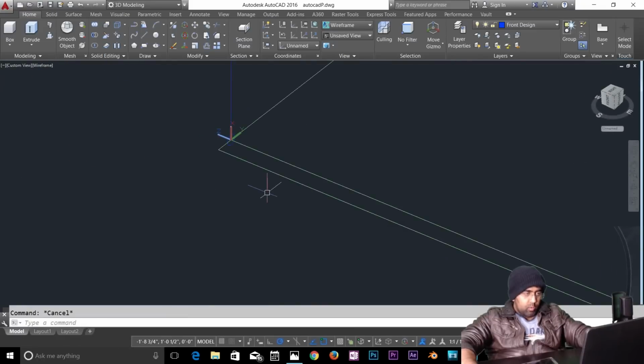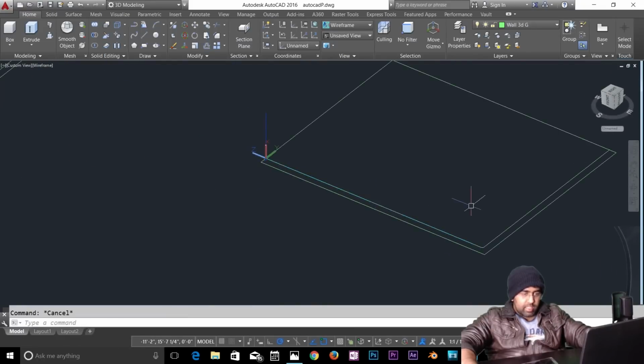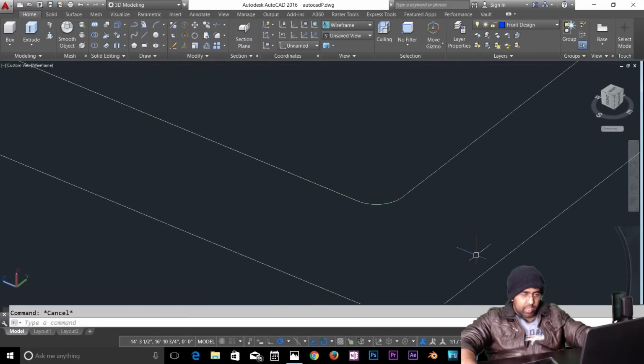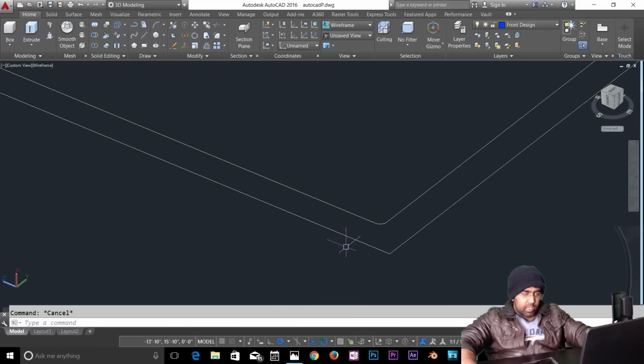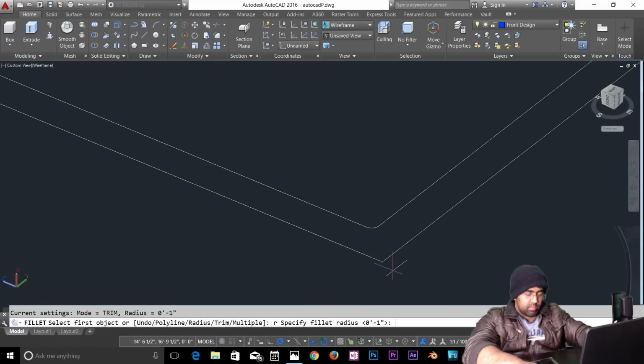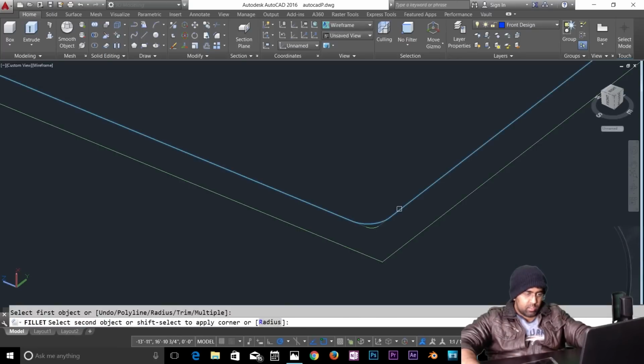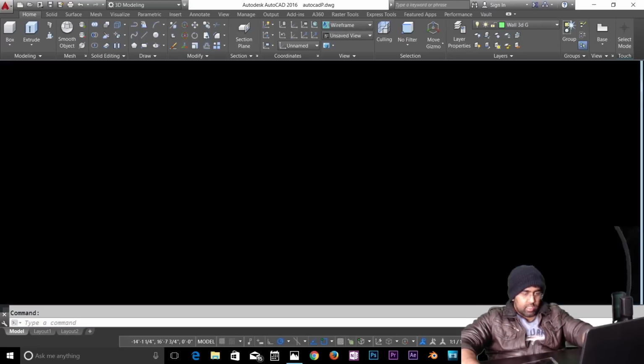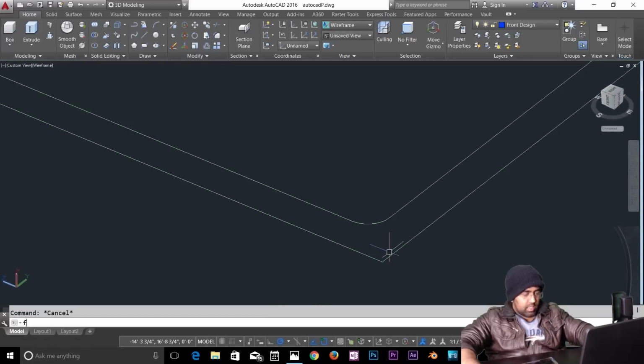So now we're going to use this path. It hasn't been joined actually, so let's fillet that with a radius, give about 3 inch, maybe. 3 inch, yeah, 3 inch is fine. So let's just try this. That was a bit less, so radius, let's say 6 inch.